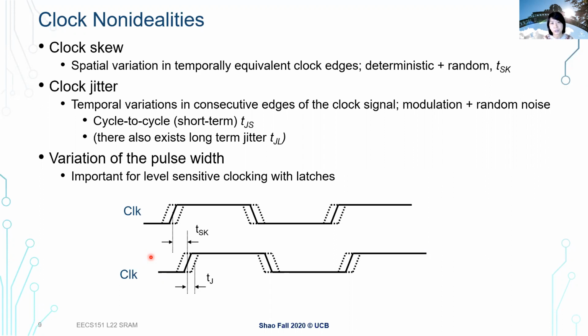So that's what clock skew is trying to measure. When you hear people talking about clock skew, they're talking about two clock signals, each used to power or trigger one of the flip-flops, and whether those two clock signals are synchronized with each other.